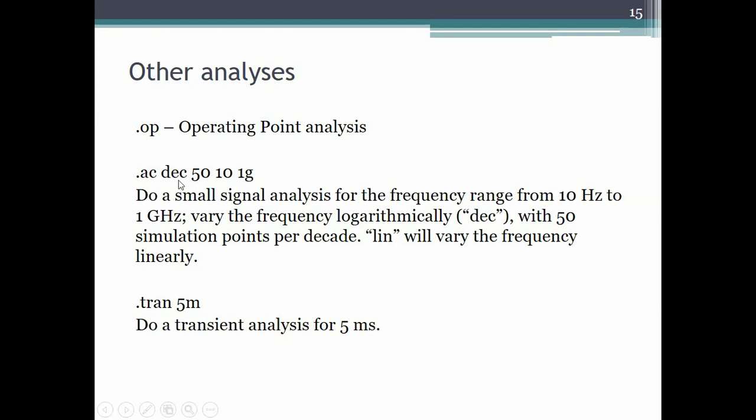Instead of DEC, one could use LIN, which is a linear variation, and that is used when the frequency range is much smaller. Typically for our purposes, when one is trying to simulate resonance circuits.